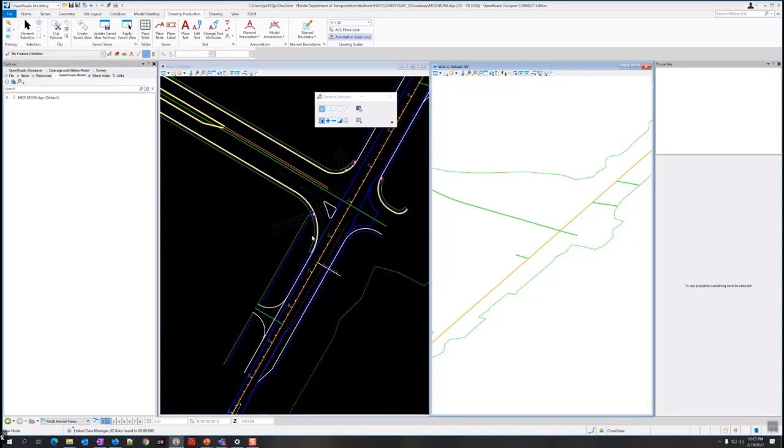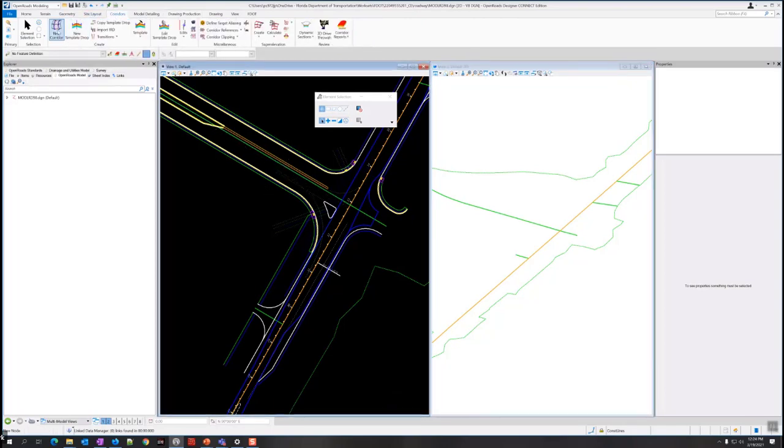All right, so let's see. Let's go ahead and save settings. I think that's ready to go. We should be ready to create the corridor for this. All right, so we're going to go to the corridors tab of the ribbon again. Back to new corridor. And this time the baseline is going to be the US 98. I'm going to reset for the active profile.